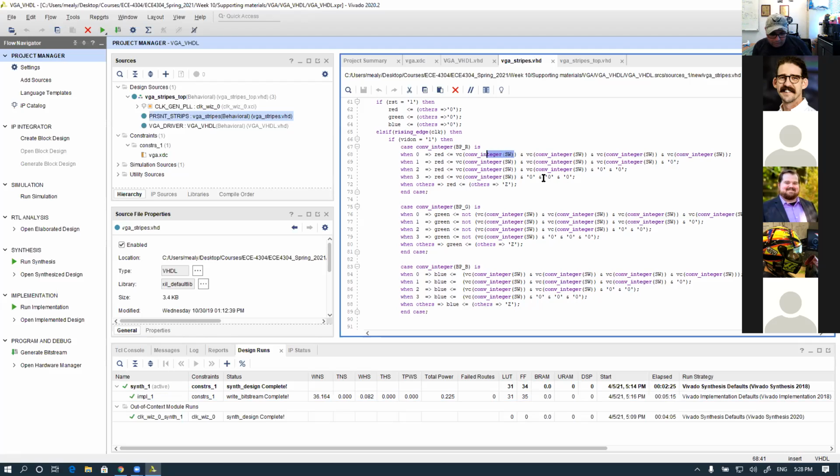Then we moved into the VGA. We figured out the VGA is an analog interface. That means you need to write a digital interface co-designed with the analog interface, fixing the timing issues using counters for defining the horizontal and vertical behavior with associated numbers coming from the manuals and the VGA designers. Then we built the VGA, which is turning on the screen with the ability to write something in the display area, which is a rectangle or square or whatever you want to call it.